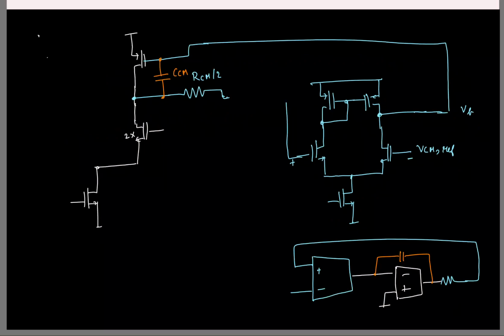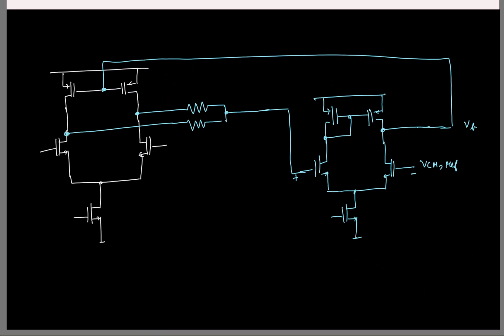And in the common mode half circuit, you see that this capacitor has to come across the gate and drain of the PMOS transistor. Here I have two PMOS transistors. So where can I put the capacitor now? Gate and the drain of? I mean, is the problem clear?